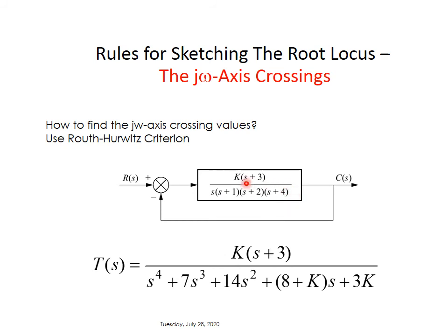And then if you remember, there will be 2 poles that will cross the j omega axis, right? And those are the poles at 0 and at -1. So please refer to that example in the previous slides. The -2 will go to -3, -4 will go to minus infinity, and the -1 and 0 will go toward infinity in a certain direction, following an asymptotic line, and they will cross the j omega axis. So we want to find the crossing at which these two branches will cross the j omega axis, right?